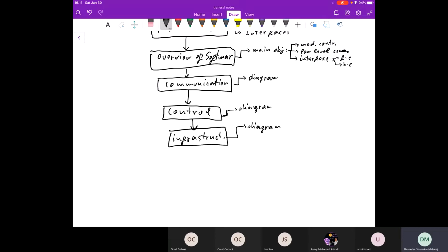Then we show the flow of data. In communications, we will show how this data is organized into channels and how these channels are all publishing to one master computer, and that's the Odroid. The channel is a publish-subscribe inter-process communication model. So Arduinos publish and the Odroid subscribes.